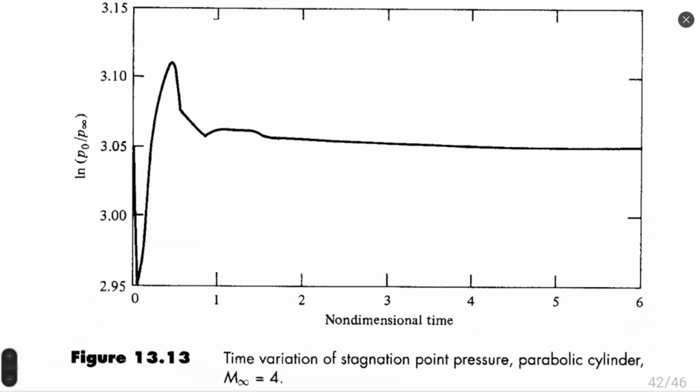Graphical representation of stabilization. This is stagnation pressure used as stabilization criteria. Also, as one of possible parameters, we can see variation of stagnation pressure. Or it's, I forgot this word, sorry, relative stagnation pressure, relative to infinite pressure, because we must have some reference point.